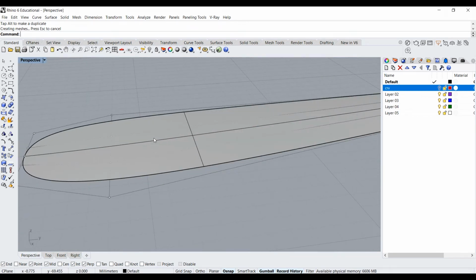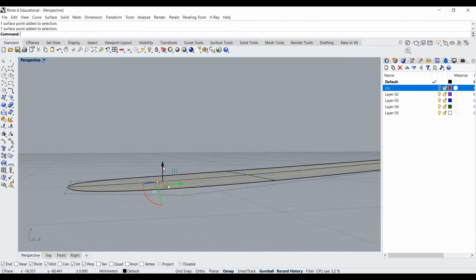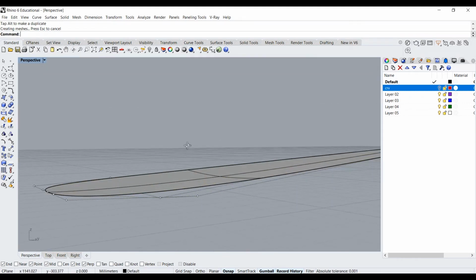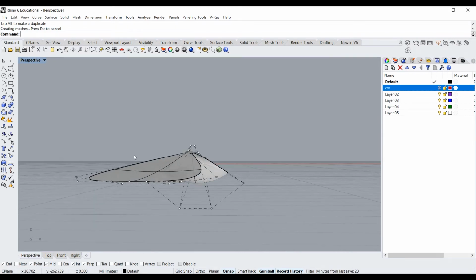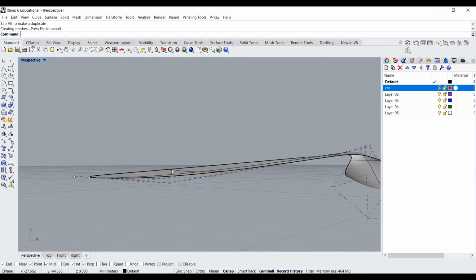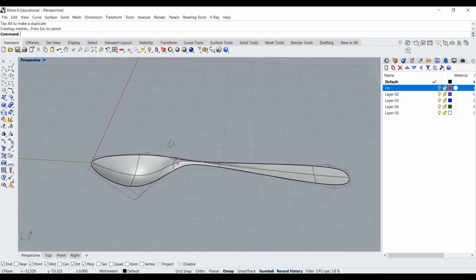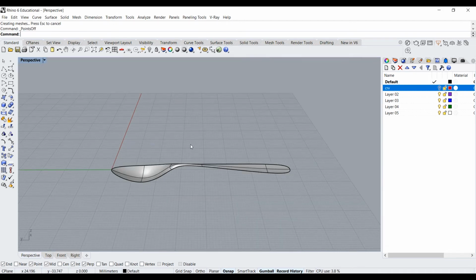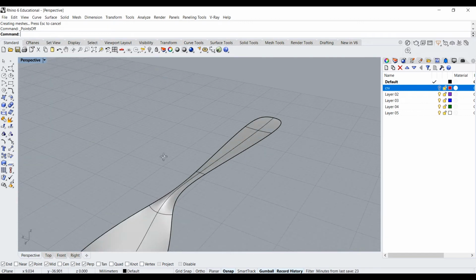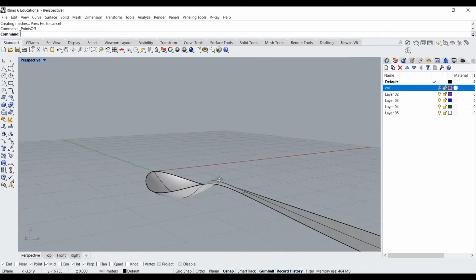And similarly at the end here, I'm going to grab these 2 points, and we're going to change the direction of the surface, actually pull that down slightly to have a bit of a concave, one of the 2, surface going in the opposite direction where your fingers might hold the end. Lovely, so F11 or right click on points off to turn your points off, and we have the big, almost there with our spoons. This is our surface edited NURB surface.